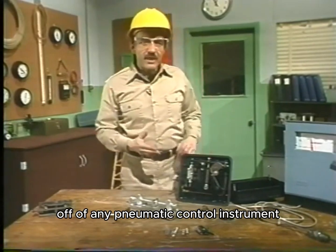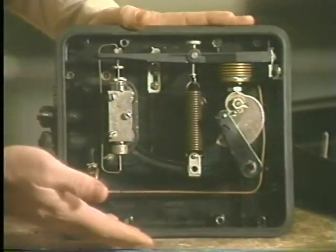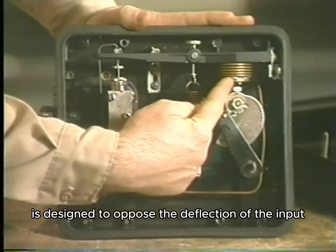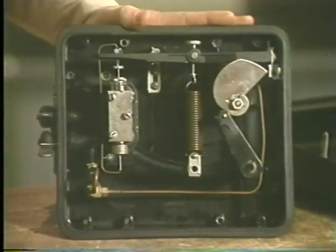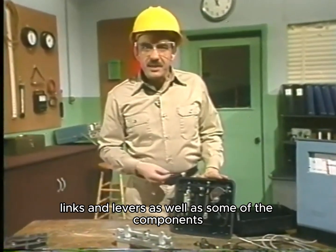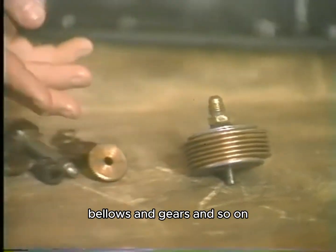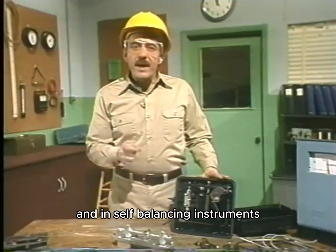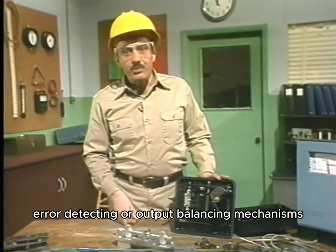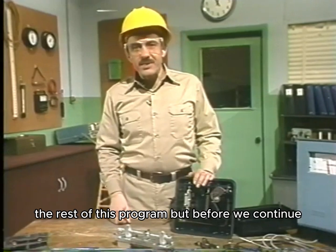So, when you take the cover off of any pneumatic control instrument, you may find any number of different shapes and sizes of springs. For example, in this positioner, this spring is designed to oppose the deflection of the input bellows and beam. Now, in addition to different springs, you'll also find a variety of beams, links, and levers, as well as some of the components we didn't look at in detail: bellows, gears, and so on. And in self-balancing instruments, these components can be a part of the input, error-detecting, or output balancing mechanisms. And we'll be looking at some of these components in more detail throughout the rest of this program.